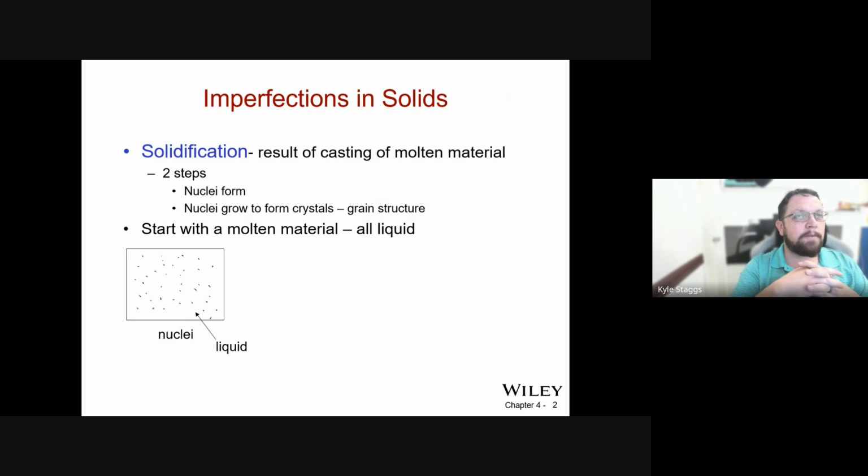So solidification is very, very important for molten material, especially because a lot of times it's easier to start with a liquid and cast something, because you can make a specific shape and it doesn't require zillions of hours of machining time and all sorts of other things. So as a processing mechanism, liquefaction and then solidification is preferable because it can allow you some lower cost manufacturing.